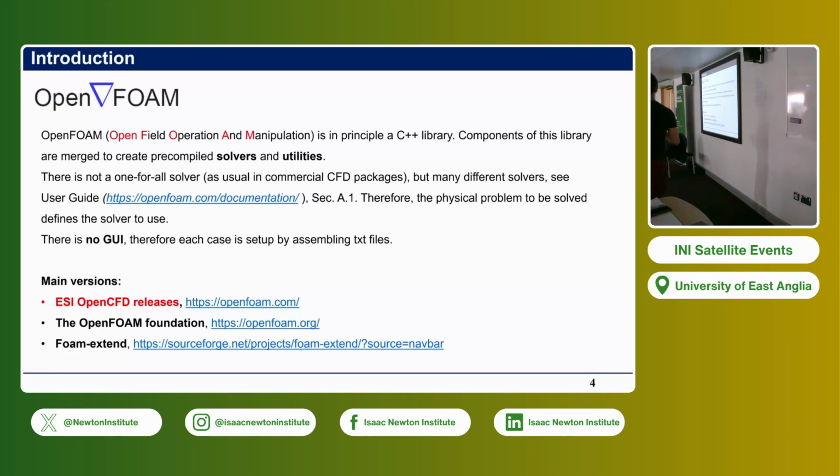I think it's mostly that if you need the basic single phase solvers, they're absolutely the same. When you start getting into, for example, multiphase flow, the version I'm using invested many years ago in a geometric volume of fluid method, whereas the OpenFOAM Foundation implemented it only in the past couple of years. And for the first version, there is also a newer library, not in the official release, but it's a big library that has all different geometric VOF and different methods to implement surface tension, including height function and all the most recent ones.